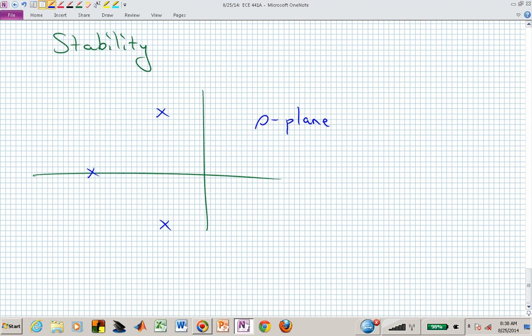And the root locus, in this particular case, might do something like that. And maybe that's not what we want. Meaning if we cranked up the gain a lot in this system, our closed loop poles are going to migrate over into the right half plane, and we'll have an unstable system. Maybe not the best situation unless you're trying to design an oscillator. And then you might want to have something very close to the imaginary axis.